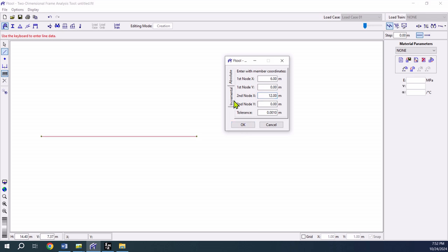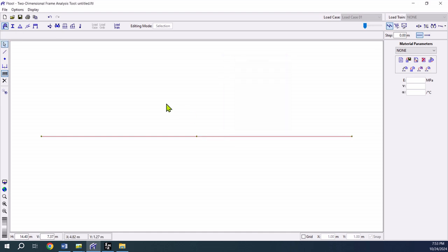See how we drew here a first segment directly. Then the second segment, I just need to click here OK, because you can see that the program has created an equal increment automatically. The first one was from 0 to 6, so the program automatically showed here 6 to 12, and if you click OK it will show you 12 to 18 and so on. So I just need 2, so I'm just going to click here again, and there you have it. These are your 2 beam segments making a beam that is 12 meters long.